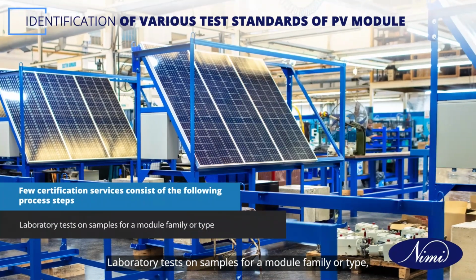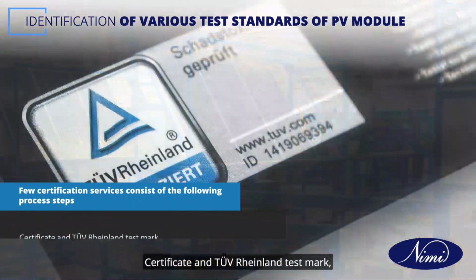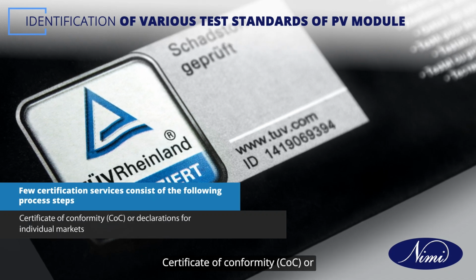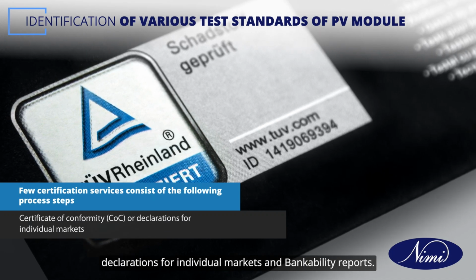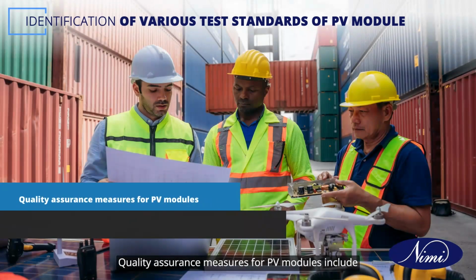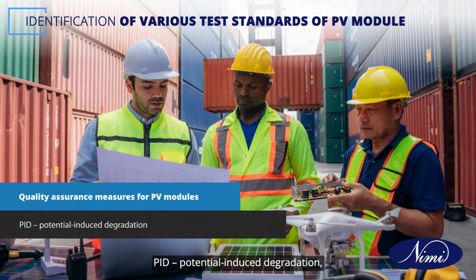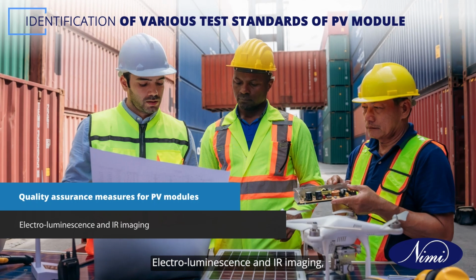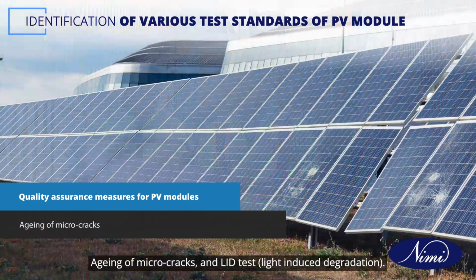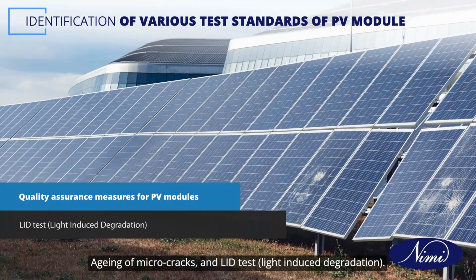Laboratory tests on samples for a module family or type, recurring factory inspection, certificate and TUV Greenland test mark, certificate of conformity COC or declarations for individual markets, and bankability reports. Quality assurance measures for PV modules include PID, potential induced degradation, electroluminescence and IR imaging, pre or post shipment inspections, aging of micro cracks, and LID test, light induced degradation.